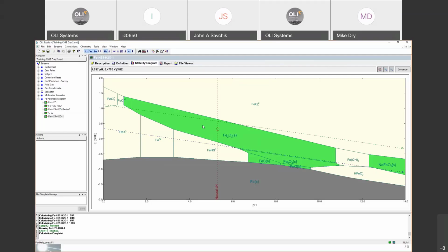So, you'll see that the oxidation reduction potential will be given, which is represented by the red circle here. This red circle is telling you the potential of your bulk solution. So if you have an environment and you measure the oxidation reduction potential and the pH, you have an idea of where in this map you are located. These are the coordinates where your material will be located.